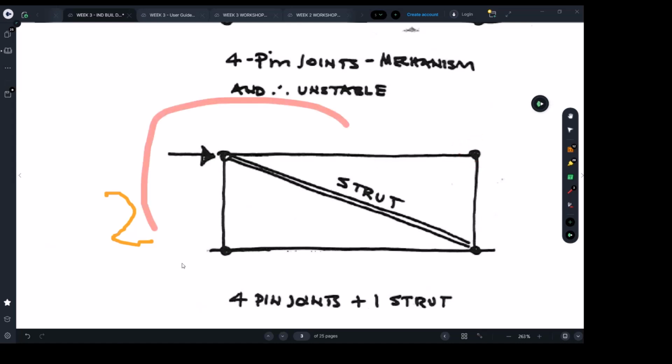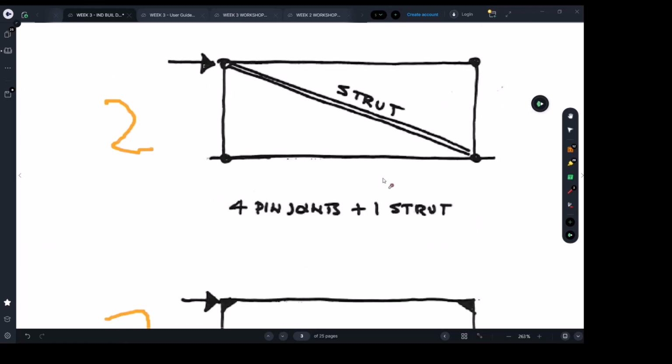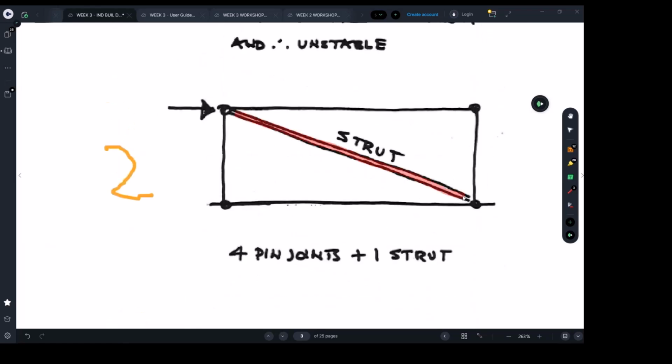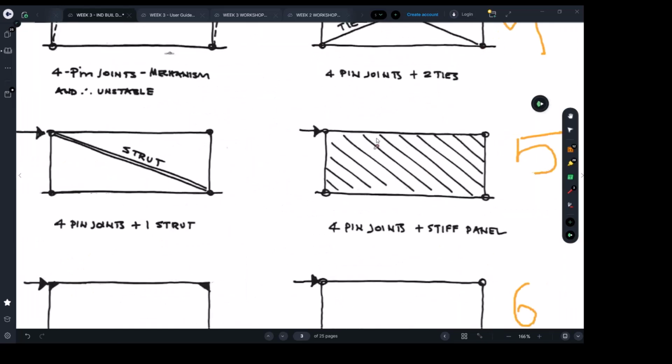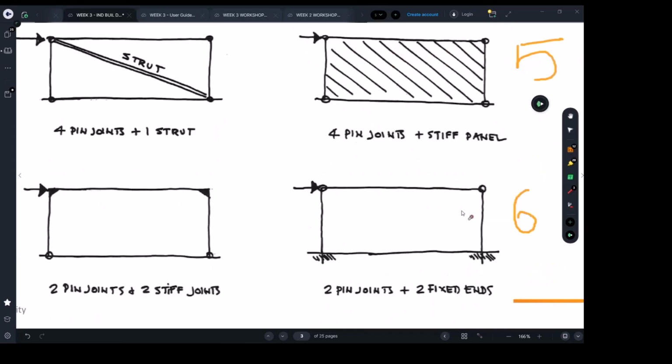However, the problem with this one is if you push it with wind load, it's going to fall down. So to keep it static, we put a member like this if architecturally possible. Another option is you build a block wall, which is maybe not acceptable architecturally. Another option, you put an X bracing. So that's what I'm talking about.